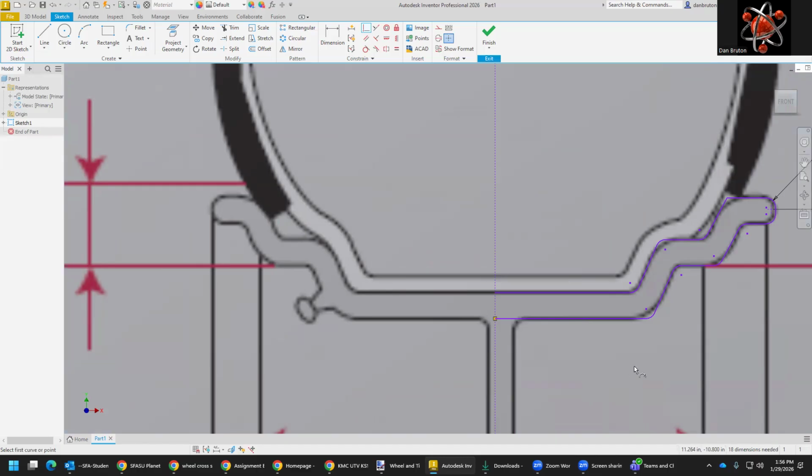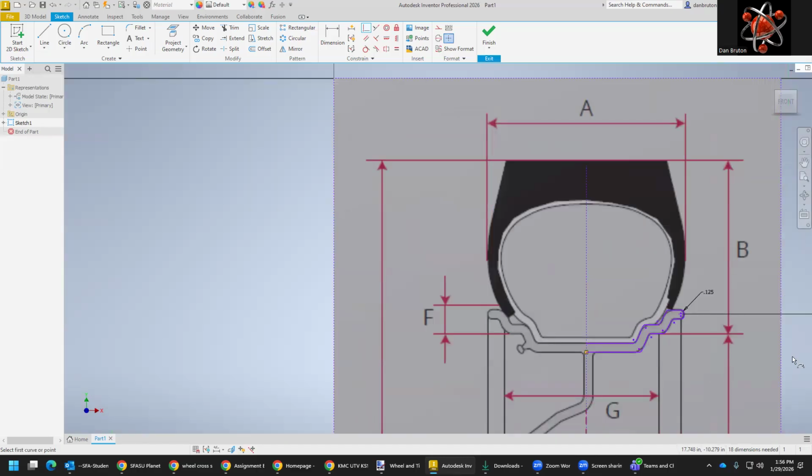I think that one's good. Here's what I'm doing again. I go out to the blue space. I'm selecting the objects here. I'm hitting control click on that line and this so that it doesn't make a mirror of those two things. So we're going to try that again. We've selected those prior. We reflect it here, and then we say apply.